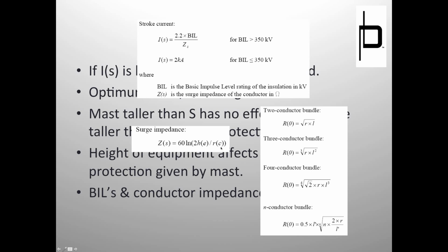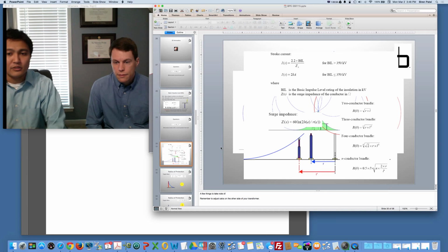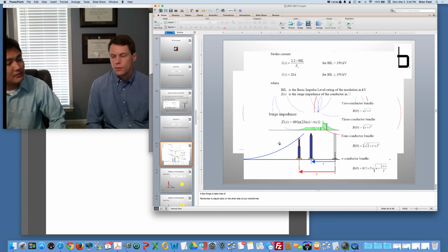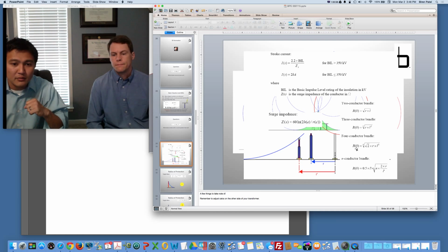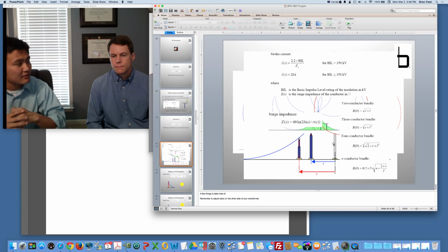But what I like to do is find out which radius of conductor would give me my worst case, my smallest sphere, and use that one, knowing that conductors that give me a slightly larger sphere, I protected against those if I protected against the smaller sphere. So just a way to reduce some of those calculations. Okay. So, any questions about what we went over there with all the different gotchas and all the different analysis? No, I think it makes sense.